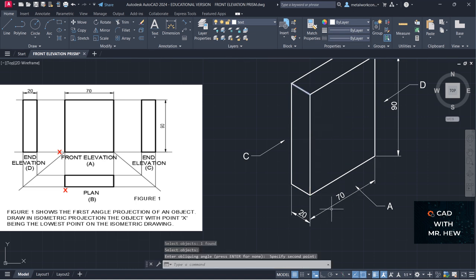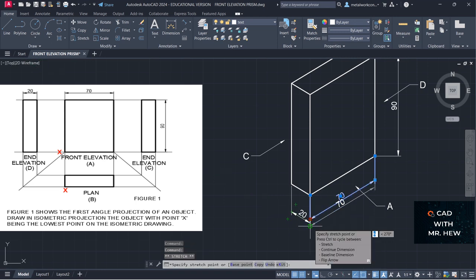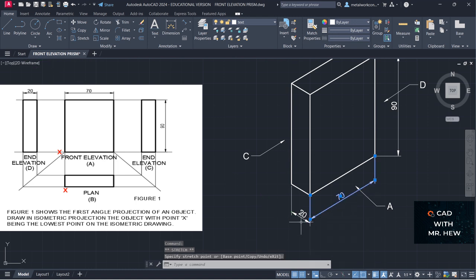See? All right, so as I indicated, if you want to align it to that one, you're going to turn on snap. So we click on it, and we click here, we can move it down like this. Or we can move the 20 up. So if we click on the 20, and we click here, see we can align it to that one.